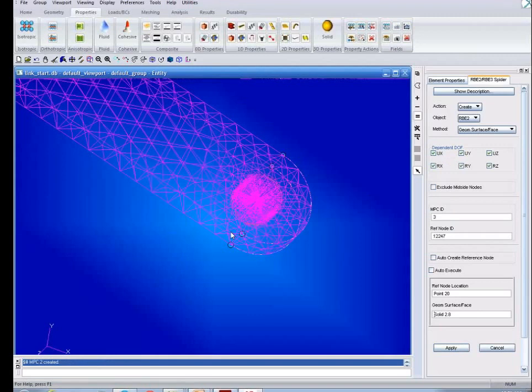There's one more step we have to do. So remember these 2 attachment nodes. These are the really important nodes because they don't get converted into modal space like everything else. They're physical degrees of freedom. And we need to specify what those attachment points are going to be in the modal neutral file. And the way we do that is through the loads and boundary conditions.